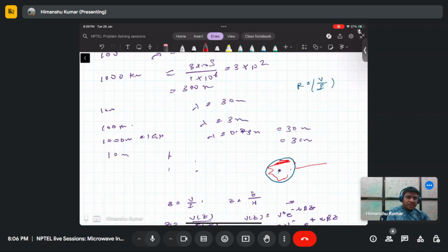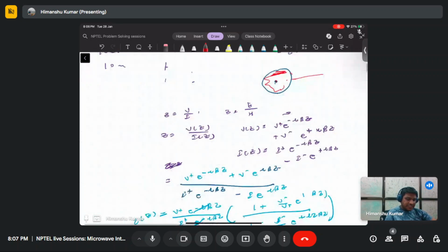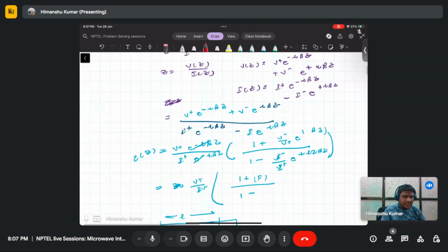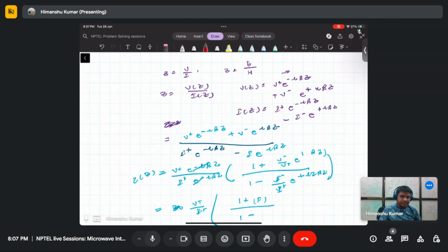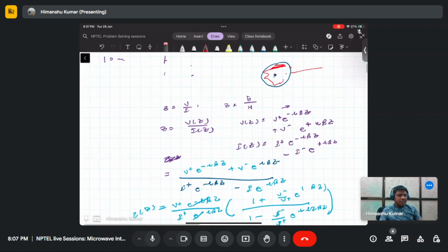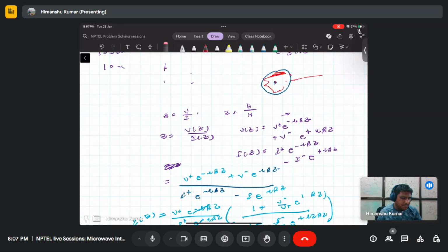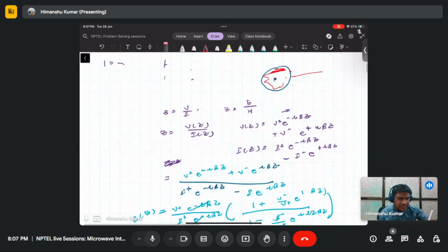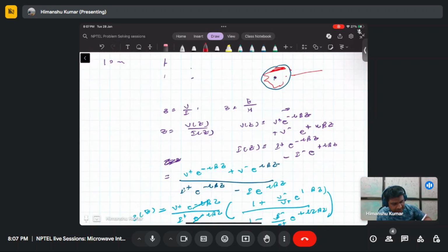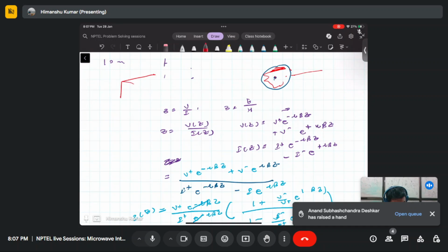You can use it as the transmission line. But still, you need to consider varying the length of this line, and then you need to consider the spatial variation of the voltage and current to calculate the impedance. You can calculate the impedance by a few different methods, and there are two ways. One is the waveguide. In the case of a waveguide, there are no two conductors present.